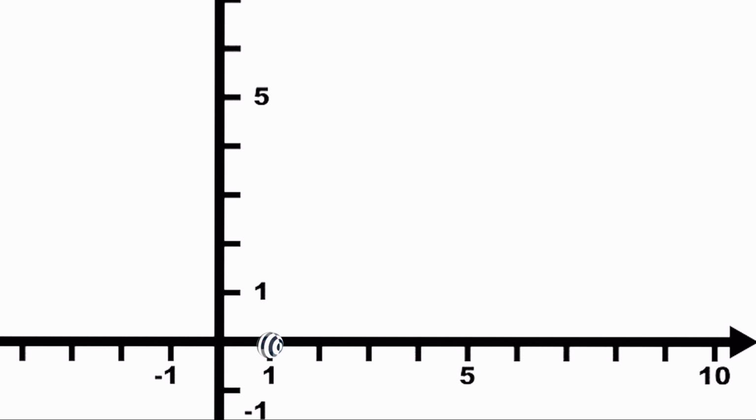This rendering also shows the sphere moving in a square. But this time the reference trajectory is not given stepwise, but like a ramp. So we increase the value for the desired position continuously. Also, the future trajectory is known to the MPC controller this time. We noticed that the movement is a lot smoother now. We don't have this back and forth motion anymore. It seems that the radical changes in speed or direction might cause the robot to behave erratically.